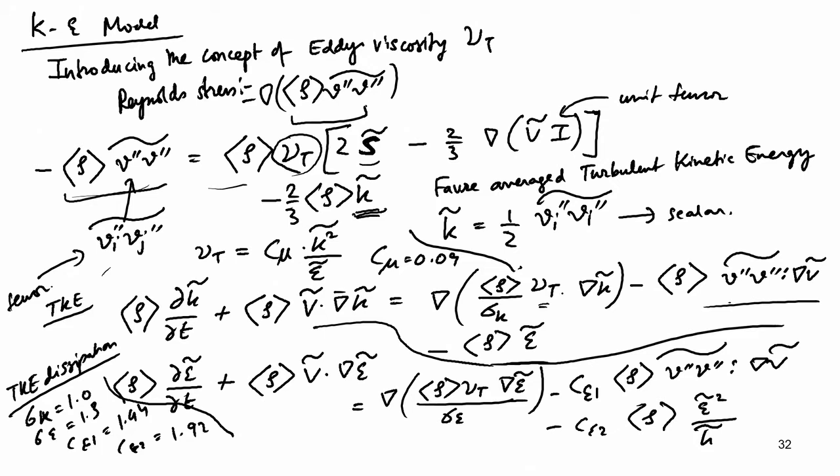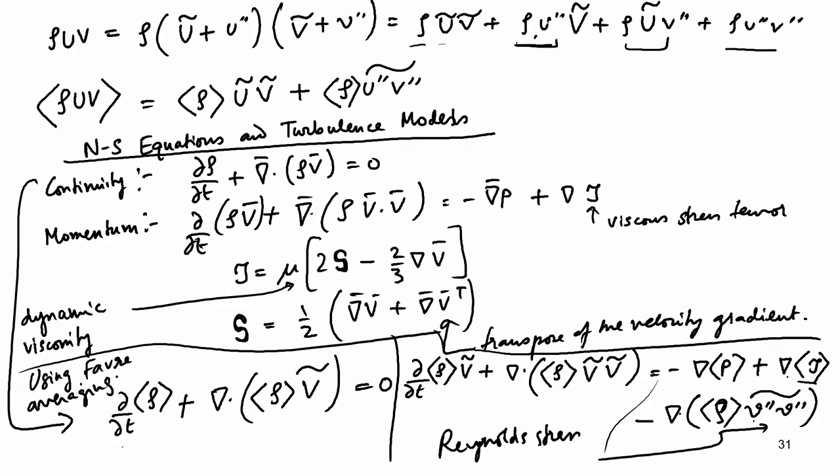But in density varying flows, typically you solve the continuity as well as the momentum equations in an average form. Of course, in an average form the continuity equation does not have any problem, as you saw. This is the form of the average continuity equation with Favre average variables. Then when you do the same thing for the momentum equation, you see that of course